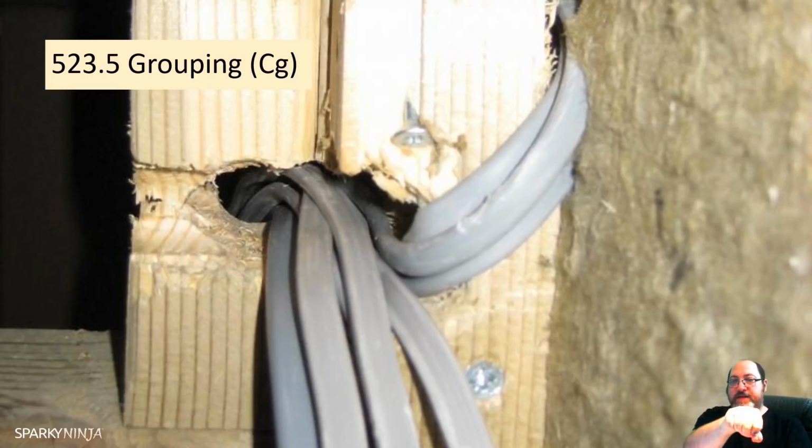Because if you think about it, let's say that my fist is a cable. It's trying to give off heat under load. And if I then put it next to another one, and they're both trying to give off heat under load, one is going to oppose the other. There's going to be a level of challenge, and so that part of the conductor is going to be restricted, and it's then going to need to be limited. That's what this is about.